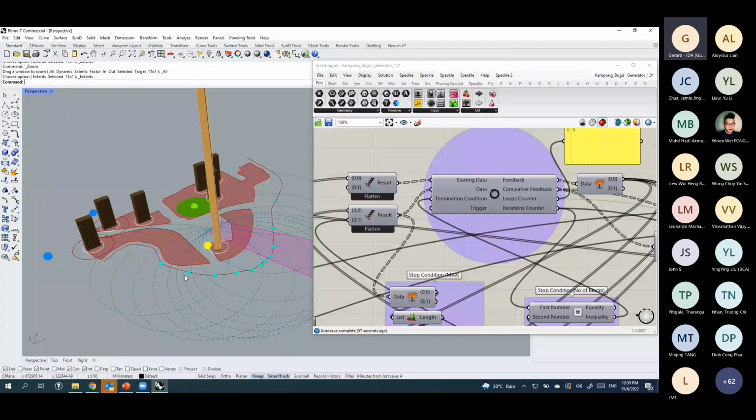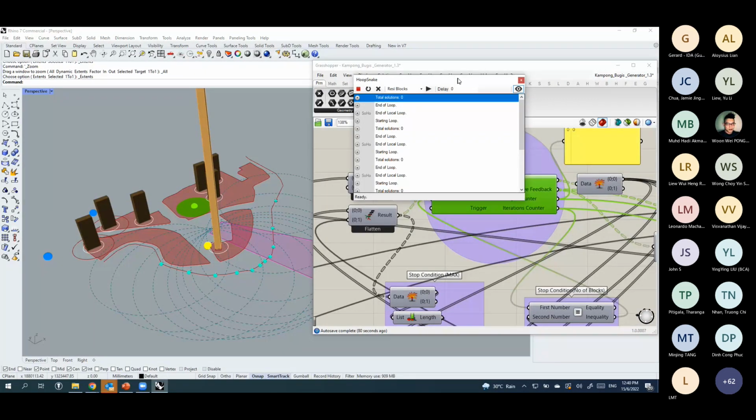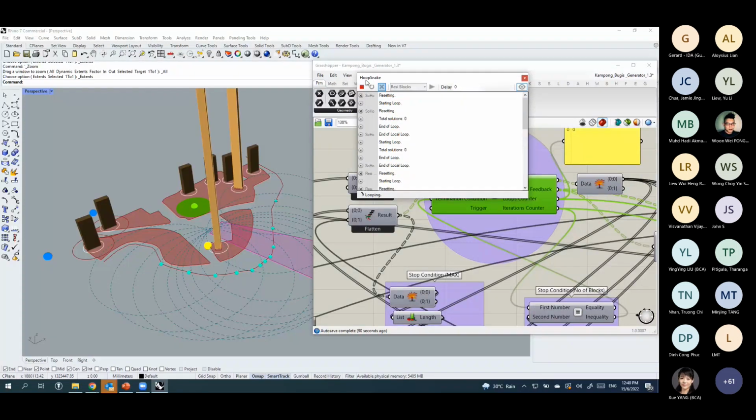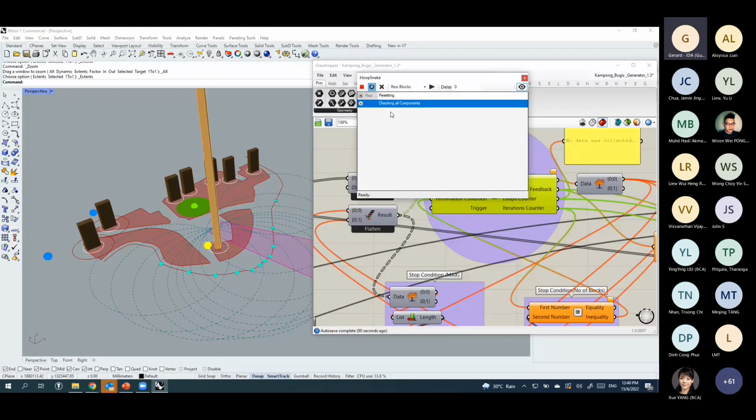So for example, okay, how do we maximize the number of residential units with a waterfront view? We look at the angle of the facade of the buildings towards the waterfront views, and the more acute it is, that means the less view they have. The wider the angle, the better the view. So we're using these kinds of generalizations to codify our design intents in geometrical terms. So once we have all that, we can actually run the script and have it generate a scenario for us.